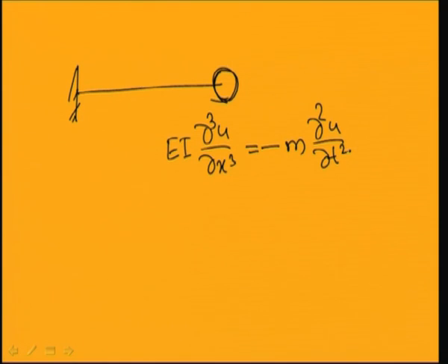So by taking different boundary conditions, you can see that you have 4 boundary conditions. In this particular case, shear force equals inertia force, bending moment equals 0, and at the left end your deflection and slope are 0. So in all the cases you are finding 4 boundary conditions. Using those 4 boundary conditions you can find the equation for the mode shape of the system.